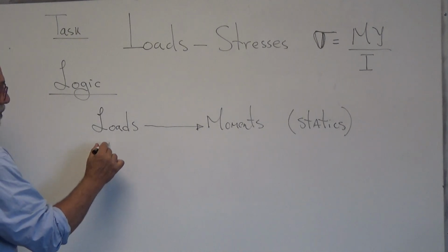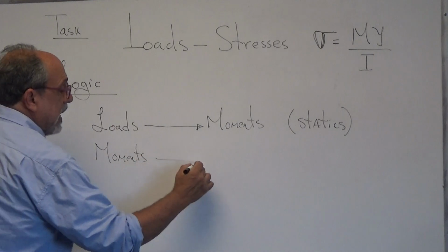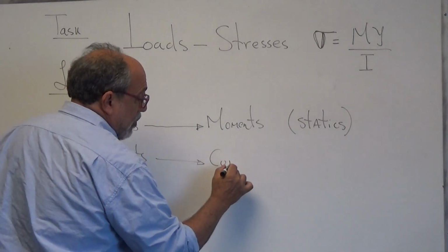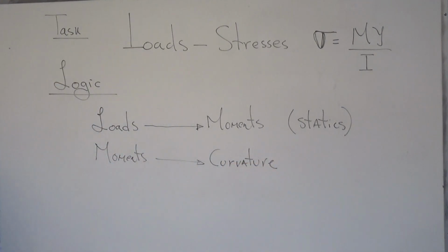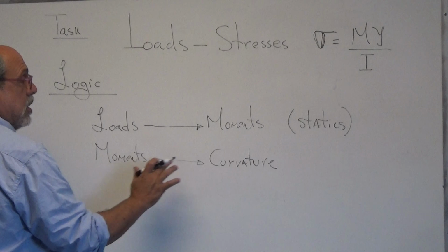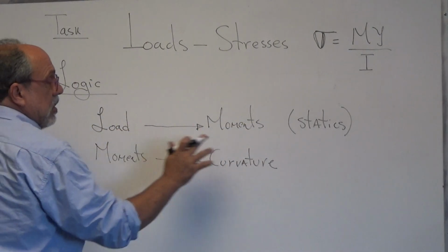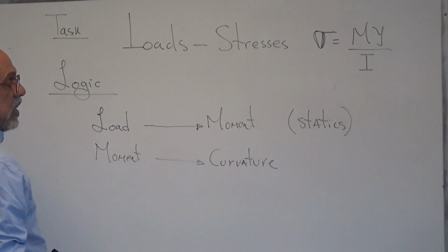Now, from moments, we will get, at a given point, curvatures. Let me just work in singular. From load, we get moment. From moment, we get curvature.